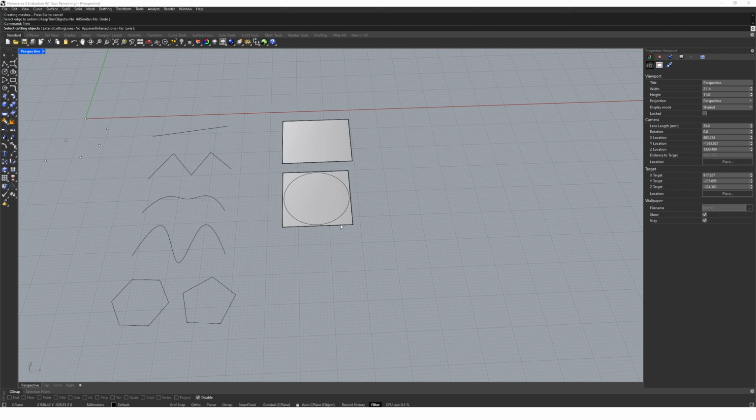I'm going to select the curve as my cutting object, and then select the outside of the surface to trim back so we get that circle again. So just remember that any surface that you create in Rhino can actually be untrimmed back to a rectangle. It's just a mathematical equation that's set up that's the basis for all the geometry we're using.